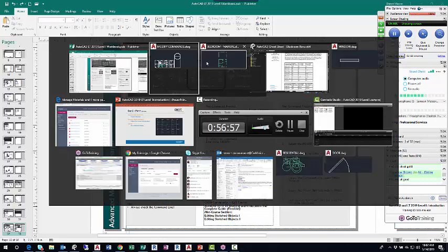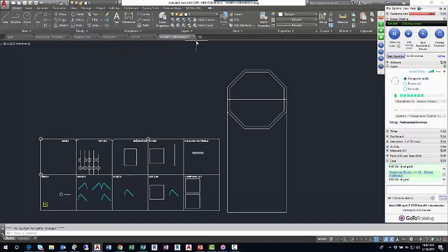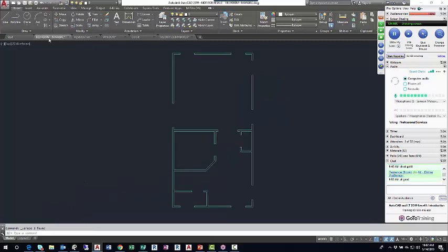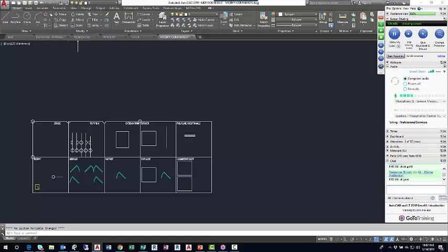So if I go back into my drawing here, modify commands, I got into the wrong drawing. I'm going to just erase this line work. I don't want to erase that much. Erase this line work. Let's say I'm recreating this floor plan, the outer face of your exterior wall. I'll start the rectangle tool, open up where Polygon is, click rectangle, left click the first corner, and then I'll type in my X comma Y, or X tab Y. So my X is 16 feet 6 comma 31 feet 7, enter. There's the outer face. I'll left click.